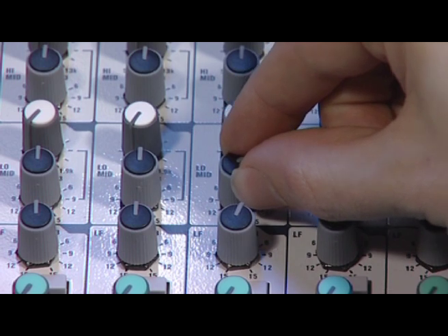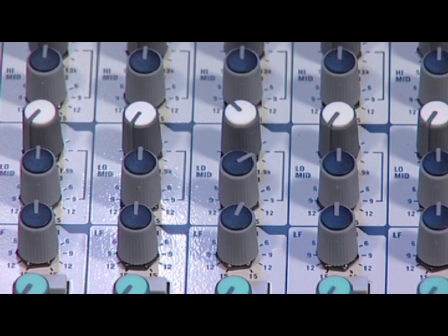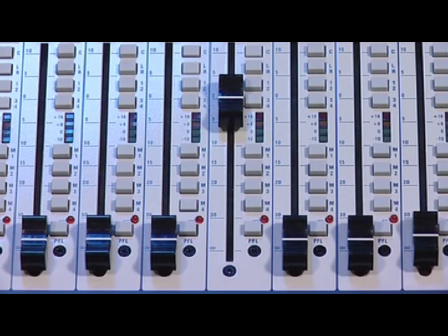Remember that EQ is actually frequency selective gain. Whenever you're boosting a frequency band, there's an increased danger of feedback, so just make sure any channels with open but unused mics are closed, and that the amplifier levels in the auditorium aren't too high.